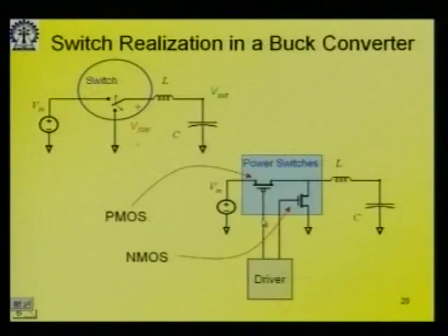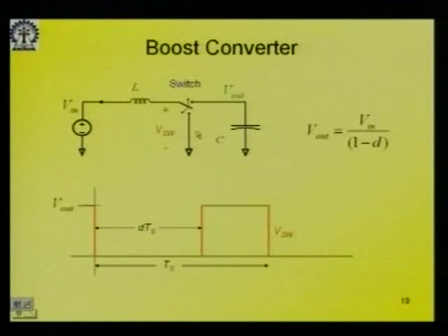Actually we looked at this as a switch. When the switch is here then this is on, and that on period is called D, the duty cycle. It is just a convention, it could have been defined otherwise also. Right, the inductor current is rising, that is the common part, you are right.